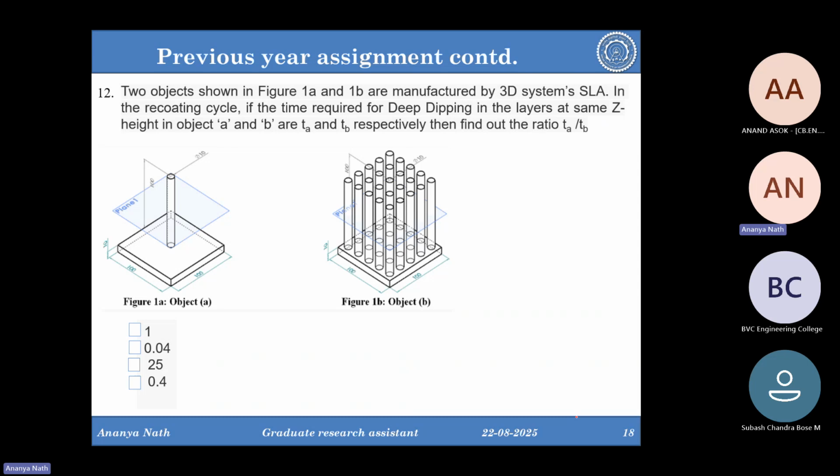where the light will be exposed onto the build plate, whether you have placed one object or 100 of the same object doesn't matter, the time will be the same because it is based on pixel activation, and the pixels will be activated at the same time, whether one pixel is activating or thousands of pixels are getting activated. So whether it's 1 rod or 1,000 rods, the time will be the same, the ratio will be 1.